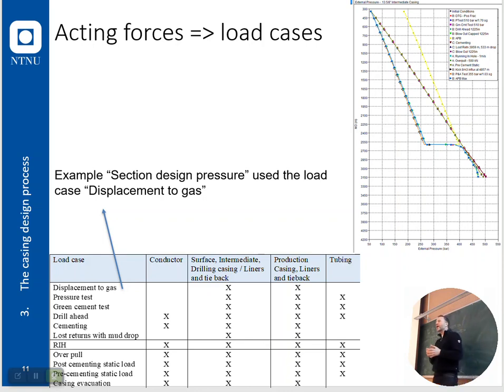And typically the strength as it starts to become solidified is the same as you guys have experienced when you have been at the beach. You hold the sand on the beach and you can form it as a snowball, right? And that's the cement when it is solidified but not entirely set up. It builds strength and it bonds, and it's only able to take any load after the setup time, designed to be anything from 3-4 hours to 6 normally.